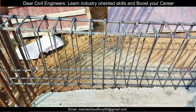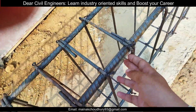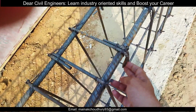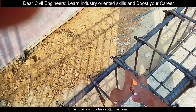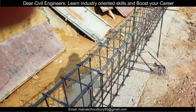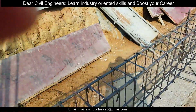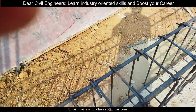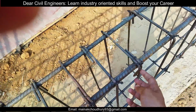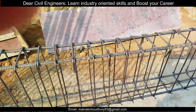Okay. The next thing you can check is that the stirrup should be bent at a 135-degree angle like this. Here the work is in progress. As you can see, this is bent, but in some stirrups bending is not done yet because they are doing the work. So you should check that the stirrup is not straight like this. It is bent at a 135-degree angle. It helps in resisting earthquake loads.